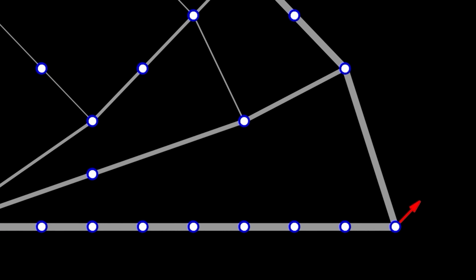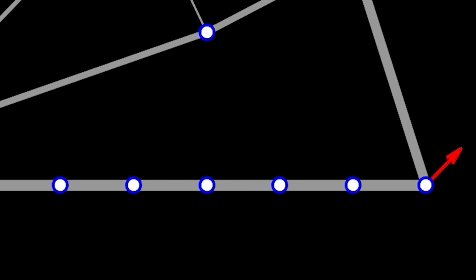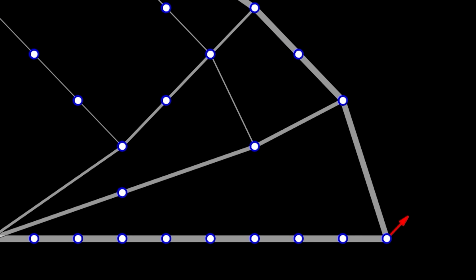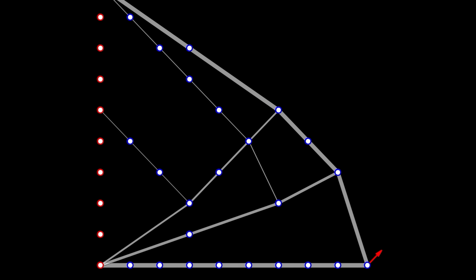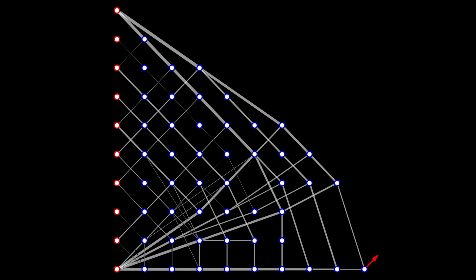Although our truss program calculates the optimal truss for a given ground structure, the solution seems a bit impractical, at least sometimes. This is because there are very often nodes that are not fixed by additional bars, which implies a strong potential deformation of the truss if forces are applied to these nodes. Such a truss structure is simply not robust against perturbations. A better solution would look, for example, like this. However, this is only an approximation to a more robust solution that I've calculated using a simple heuristic.